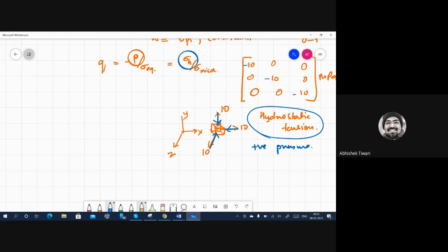Yeah. So hydrostatic stress and sigma Mises, that ratio represents the triaxiality, we also call it. We also call it constraint, but constraint is a vague term. So the technical term for this is triaxiality. Okay. So how much triaxial stress is available there? That is represented by this.